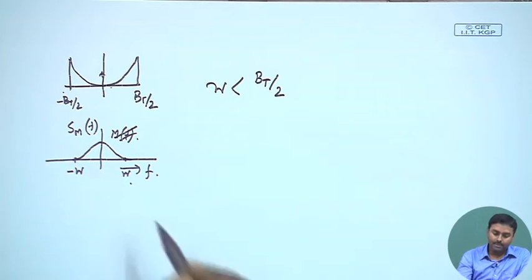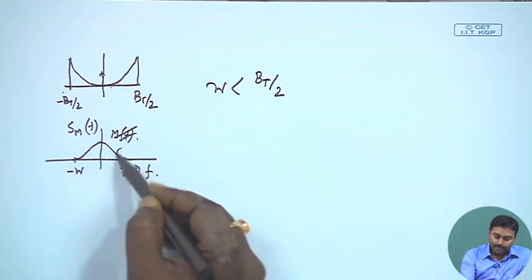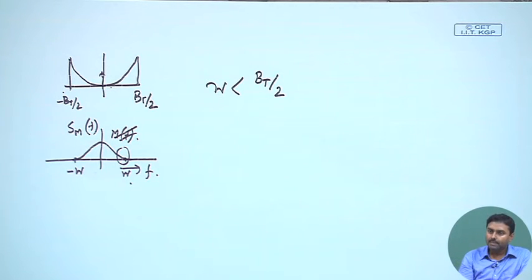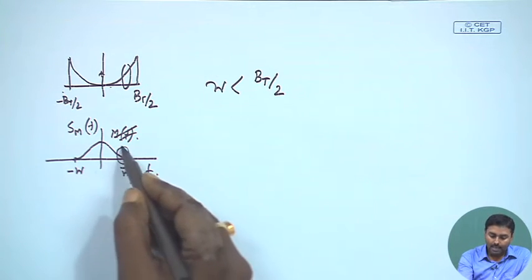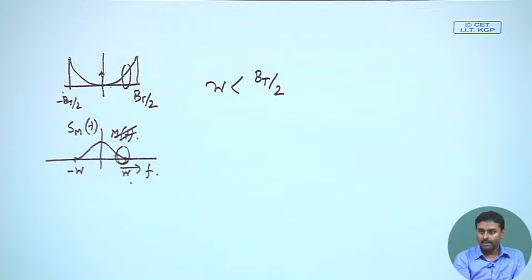So, what happens at the higher frequency side is that the message signal, because it is band limited, will have a lesser amount of power in its spectrum components. And whenever it is transmitted, after the receiver, the discriminator circuit followed by a low pass filter, what we will see at this position is that noise is more enhanced due to FM demodulation, and this is the point where signals have less power.